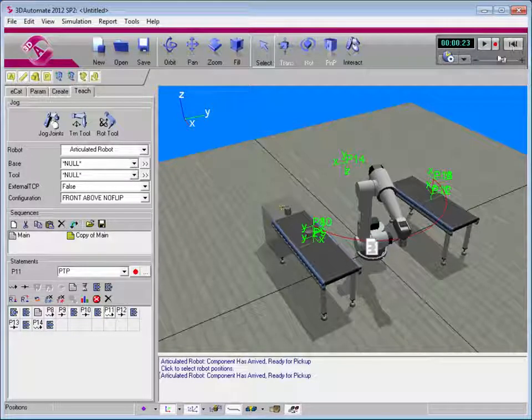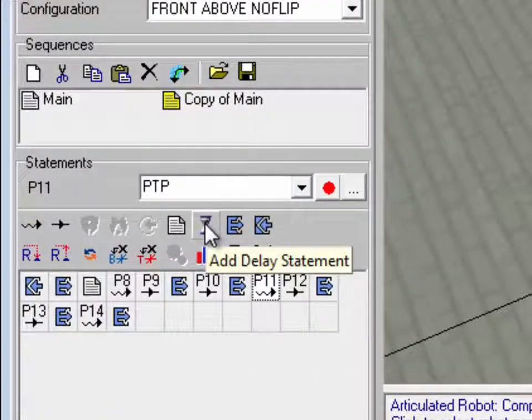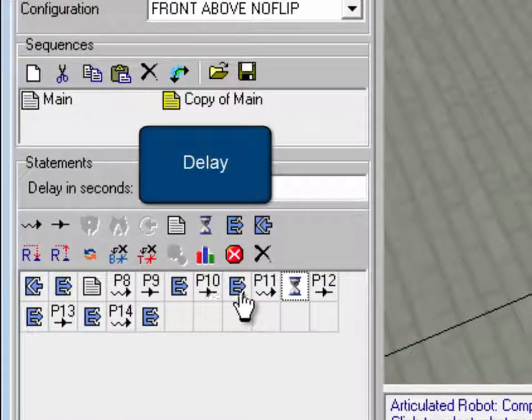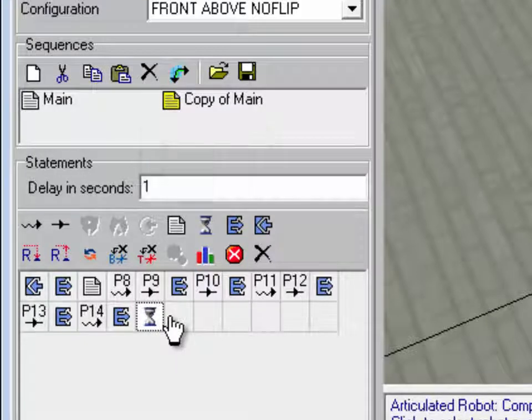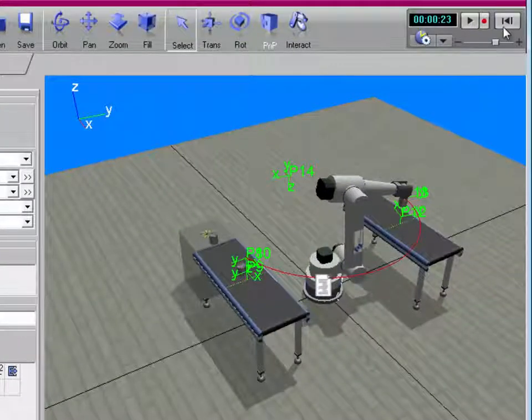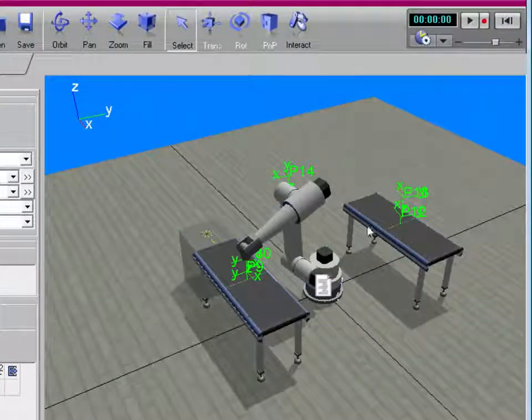All right. Now what I'll do is go ahead and create a halt statement, or delay statement, sorry. I'll create a delay. Move it to the end of the statement grid, and I'll create a delay from the robot looping its program. So I'll create a delay of 5 seconds. So I'll reset. Let's clear my message panel.